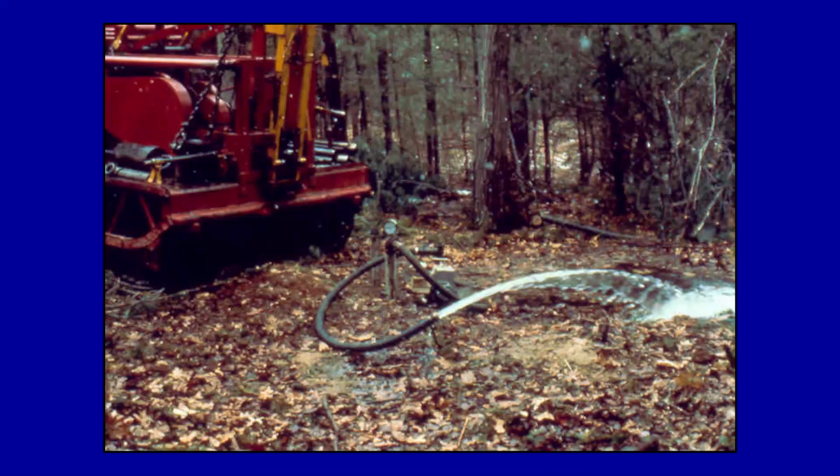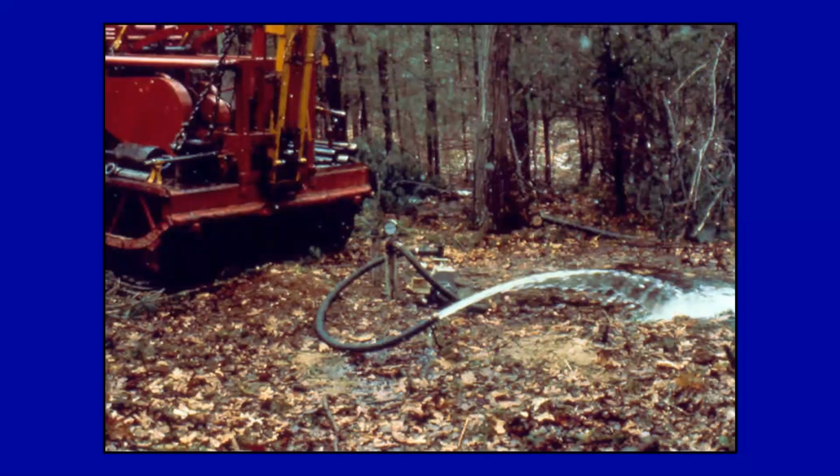This becomes important. If this pumps 40 to 50 or 60 gallons per minute, we will move 2 linear feet away and drive an observation well to the same depth as the test well. Here we may choose to put a different slot size screen in, usually coarser.